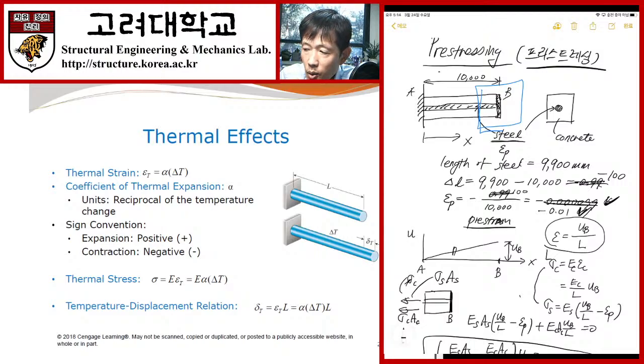So make sure that when you check the compatibility, we don't care about the stress or the forces. Okay? We check all the strains, the actual strains. We don't care whether the strain was caused by the stress, by thermal dilatation, or by humidity change. We consider only the total strain. Only the strain caused by the stress is subjected to Hooke's law. That's the key point to understand this thermal effect chapter. Is it clear?